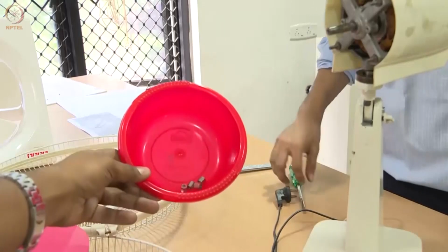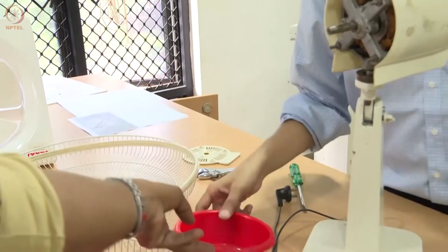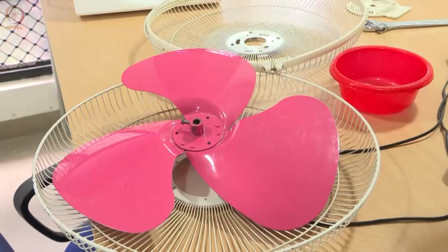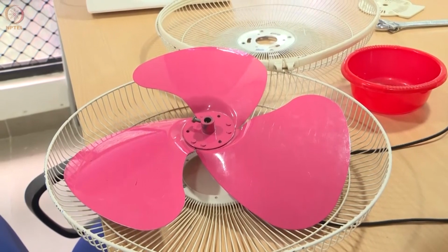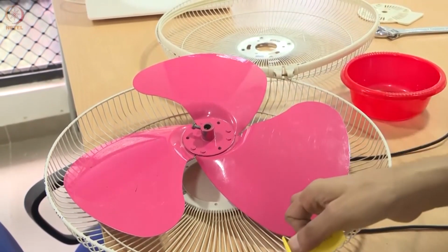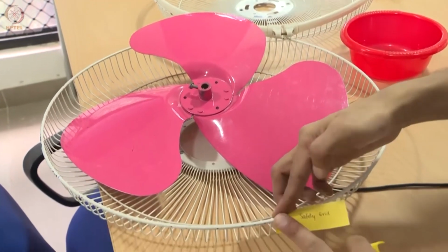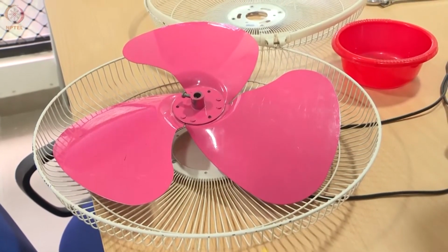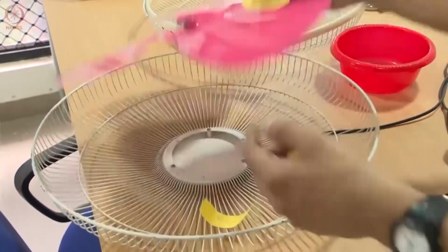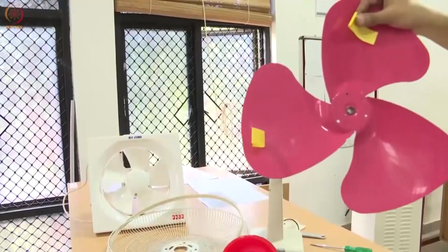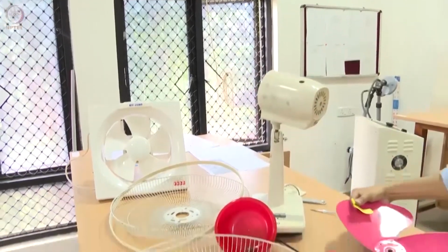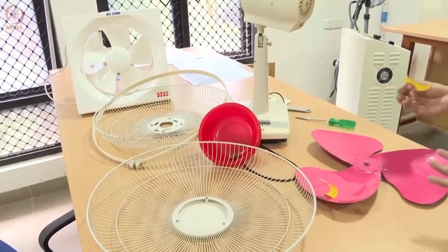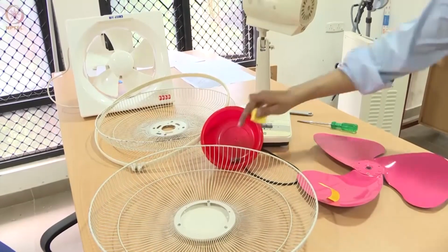It also helps to have small stickers in place so we can label each and every component. We'll do a functional diagram later, so it's better to properly label each component and keep them in a proper order, and then photograph the entire dismantling process, so that if we have any doubt, we can always go back and refer to it when we put it back together.